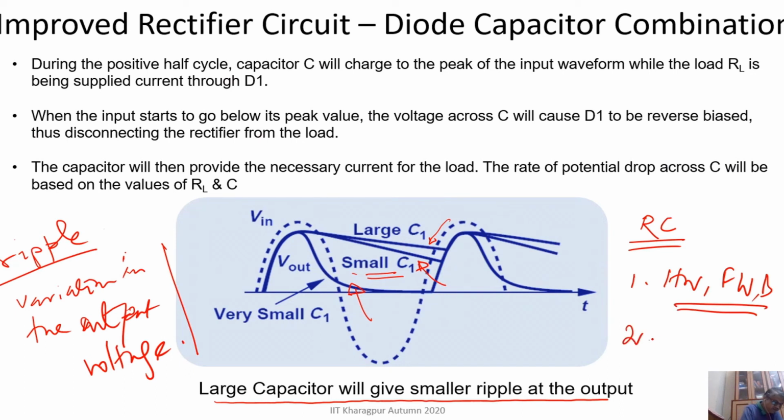And also if we use an RC filter circuit, or even with the inherent leakage path in any real capacitor, this RC time constant will dictate how much decrease in the output voltage will take place.